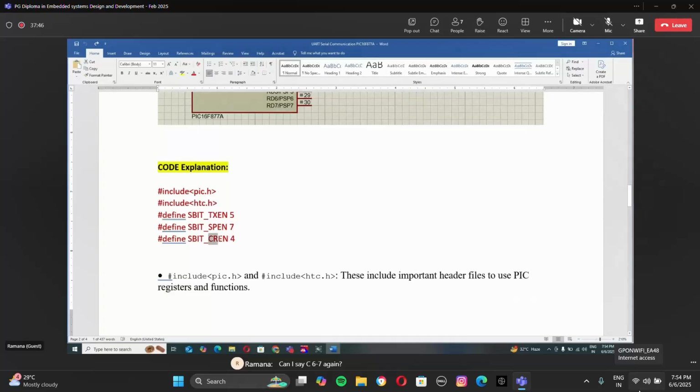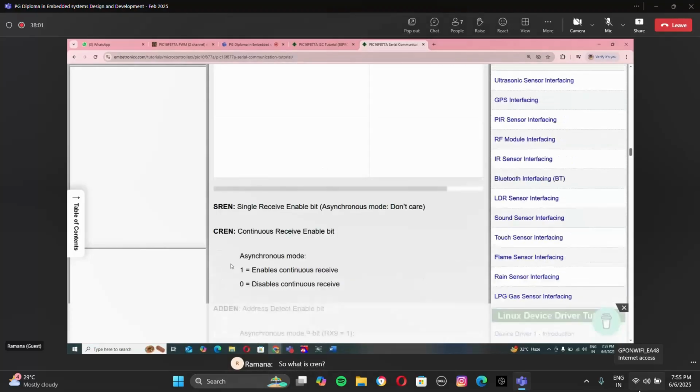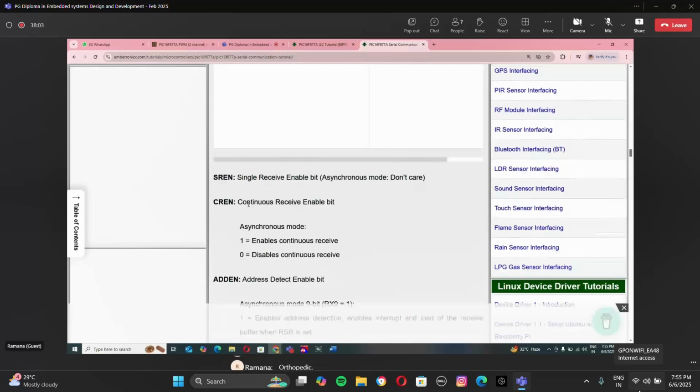Another one is CREN. Set bit CREN, the fourth bit. We'll see. It is here. So what is CREN? Fourth bit. We are making CREN enabled.